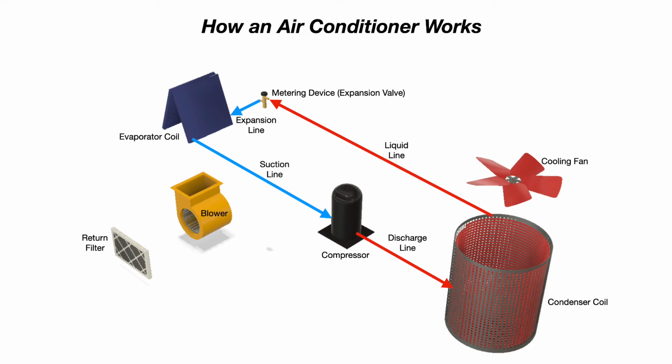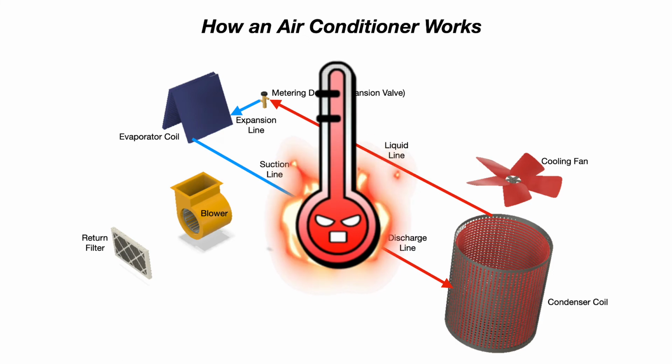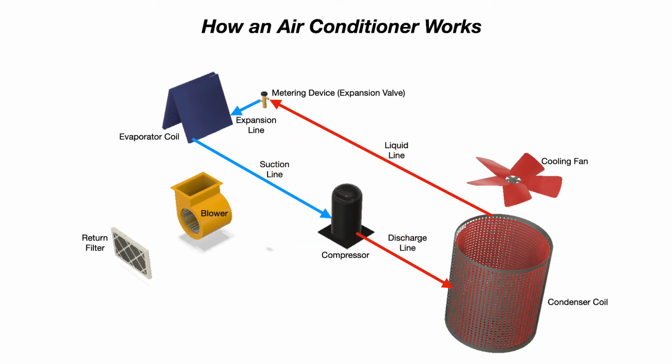So how does that work? Well, as refrigerant flows into the indoor coil through that reversing valve, it's going to give off the heat energy that it collected outside. So even on a cold winter day, there is still heat energy in the ambient air, and the refrigerant can absorb that heat energy.